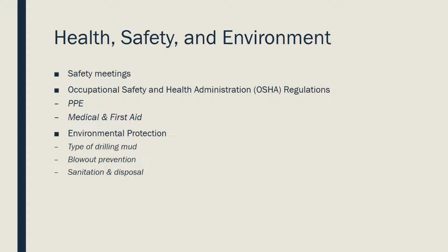If we decide to use an oil-based mud, there are certain precautions and regulations we must follow. Hazardous materials should be properly stored and disposed of. Blowout prevention should be of high concern, and kill sheets must be made in case of a kick. It is very important to follow all safety guidelines to ensure the safety of the crew and the environment.